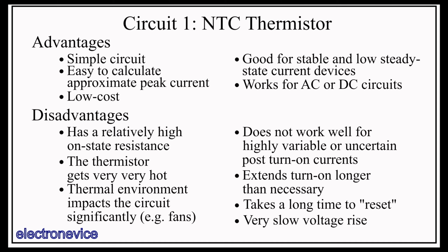All in all, I'm not a big fan of this circuit, as I prefer to have a low-resistance input power line that is stable post-turn-on. Though if your circuit is AC, its maximum post-turn-on current is pretty low, for example, a 120-volt input under 100 watts maximum, you can find a small NTC thermistor that fits the bill. If you aren't too concerned with power efficiency, and your goal is to reduce BOM cost as much as possible, then this is a good option.